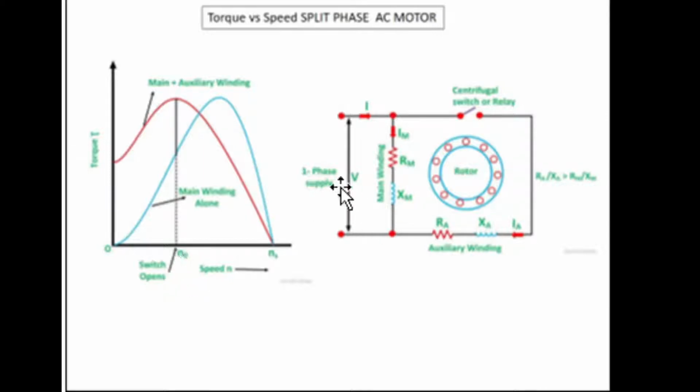So there's this switch called a centrifugal switch that, when the RPM of the motor is low, would be closed. So most of the current is being developed in the start coil at the beginning, up to some RPM between startup and running speed. Then that centrifugal switch will open up, and then the torque that's generated by the motor occurs just on the run coil.